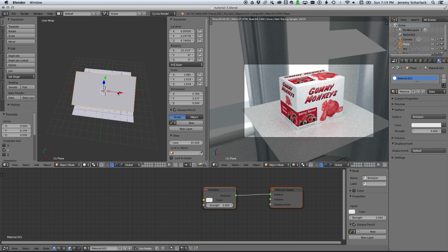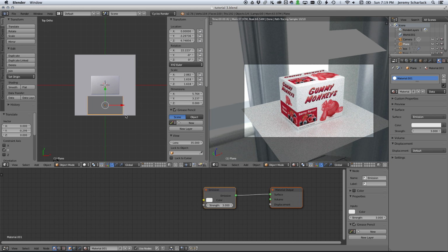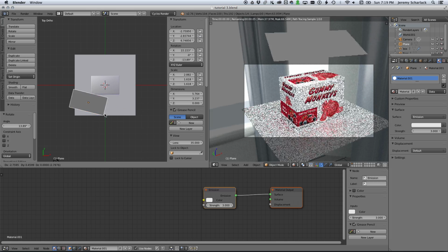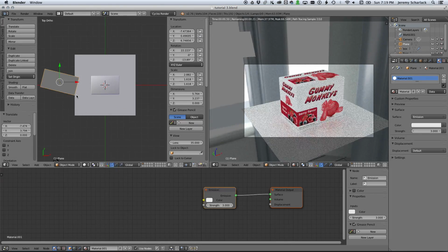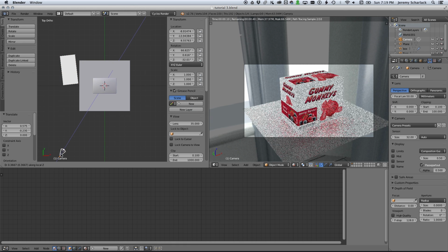And then I want to move it, hit 7 to get the overhead view, and hit 5 to get orthographic. I'm going to rotate it a bit, and then move it over a bit to the right, so it's a bit more directional. So, I'm going to pull out a little bit, G Z Z again, and then now we can start to render for real.